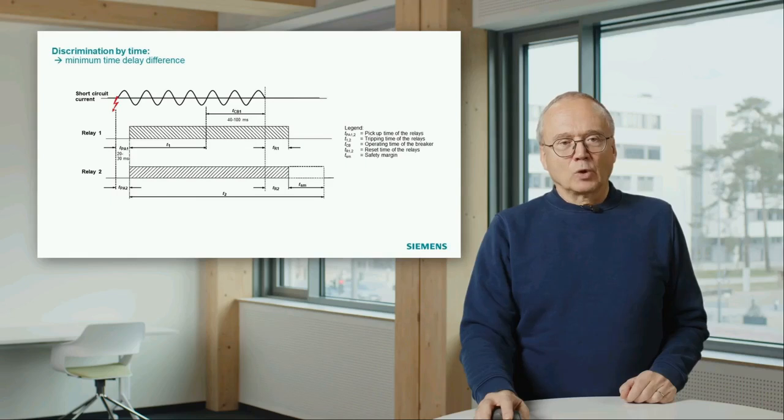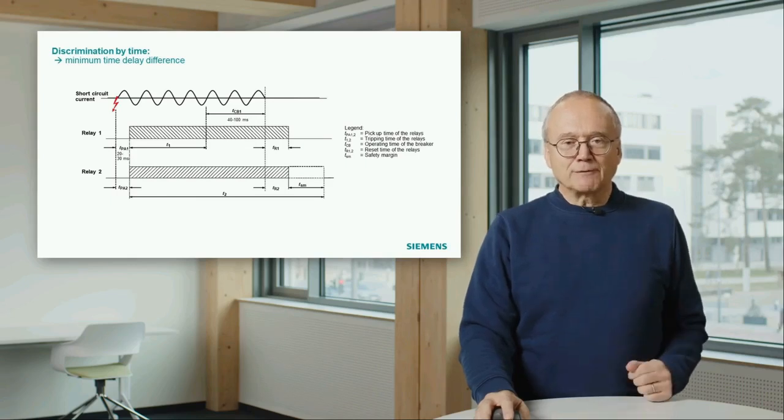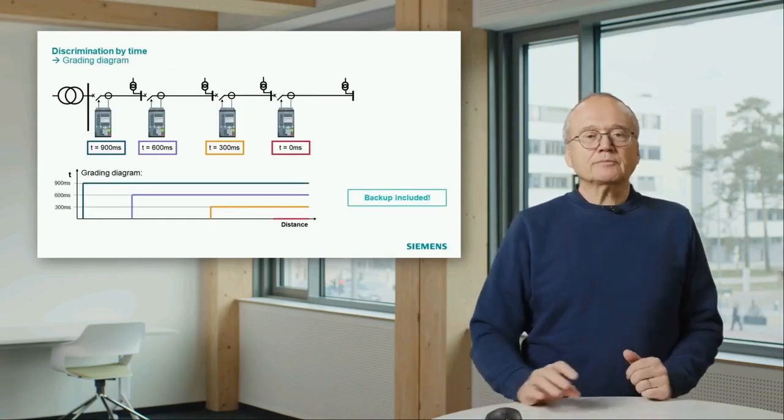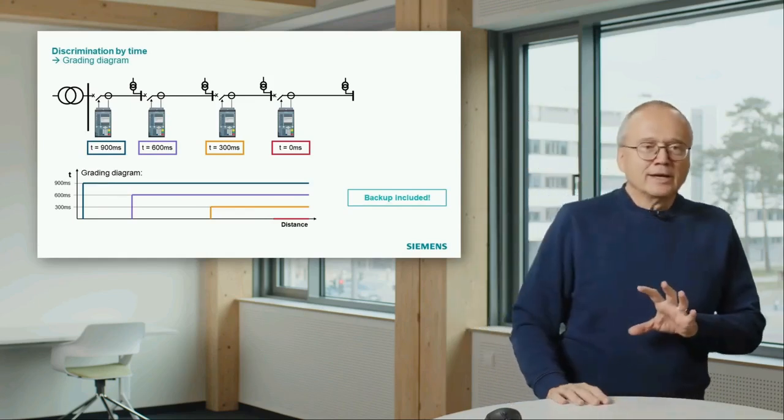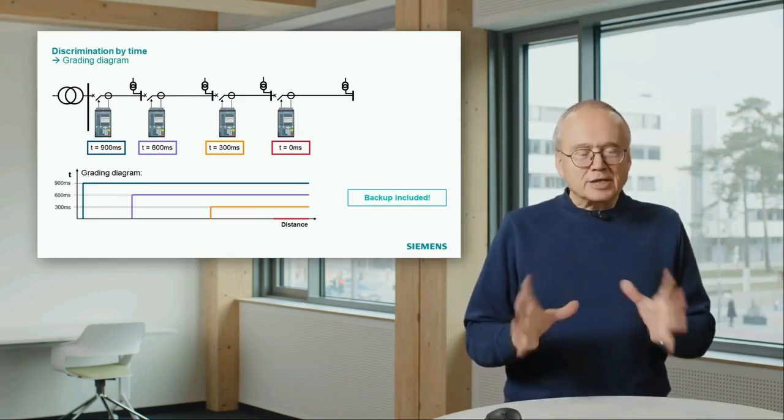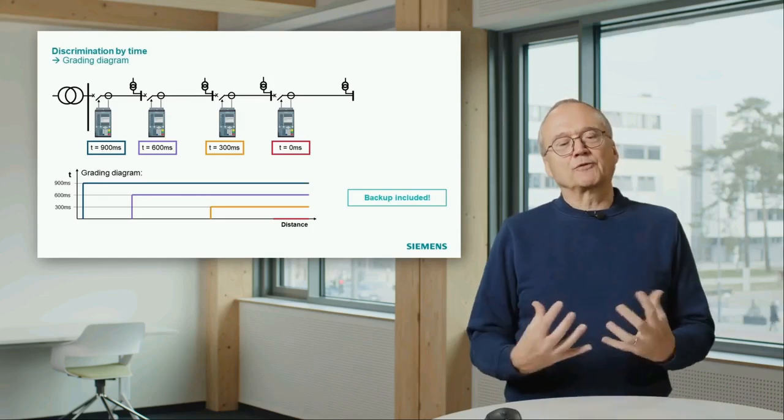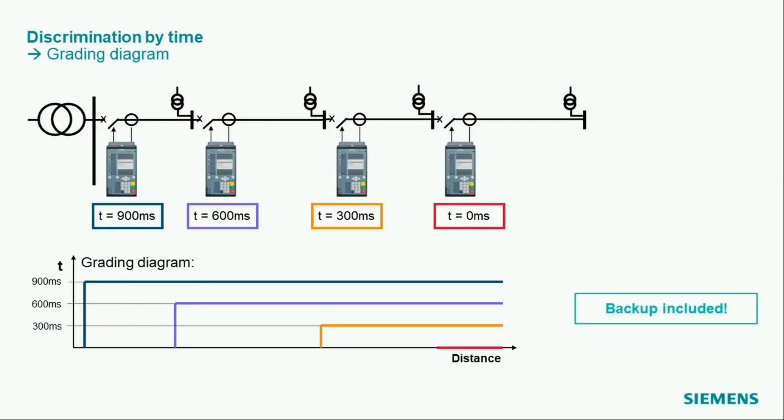Okay, that was the difference in timing. You can display this arrangement of different timer settings in this so-called grading diagram. You see here on the top of the slide again our arrangement we had with the different timer settings, and in the lower part I show the so-called grading diagram.